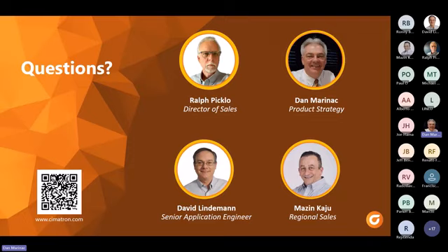They're based on a certain chemistry. For those of you that are chemistry majors, it's based on a ferrite matrix for a baseline ductility with varying amounts of other microstructure components like martensite, bainite, and retained austenite to provide strength and additional ductility. These have enhanced global formability compared to conventional high-strength steels at the same strength level, but there are some local formability challenges that arise due to the wide hardness differences in the different microstructural components.